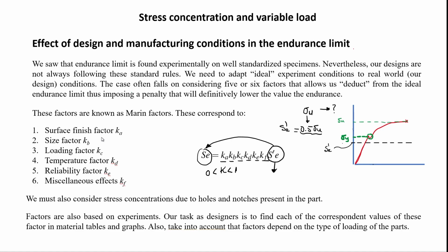Size factor, meaning that the size affects fatigue? Well, yes. Loading factor, we're going to see that also. Loading affects, obviously, if we're talking about variable load, then loading has to be one of the factors affecting the endurance limit of the material. The temperature, as we mentioned, and we can consider temperature as part of the atmosphere or environment where the part is going to be working. Then reliability factor, we're going to see later, but reliability factor means what's the degree of reliability for those 30 years you said it's going to last. For example, say, no, this is going to last 30 years. Yeah, but that's an incomplete answer. The complete answer would be it's going to last 30 years, plus or minus this much, with a reliability of this. And reliability is that something is going to happen according to what you say is going to happen, basically.